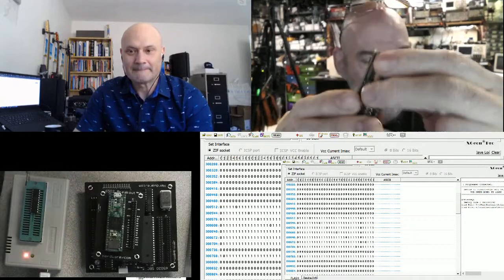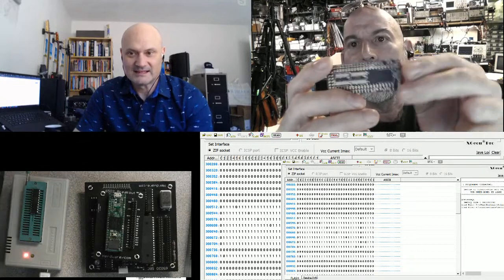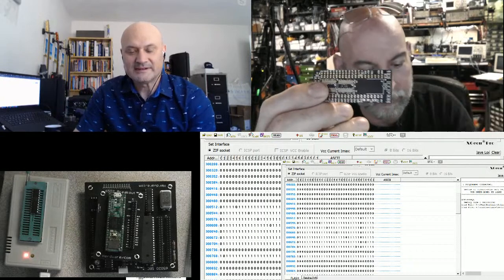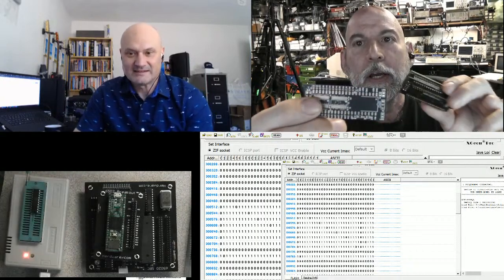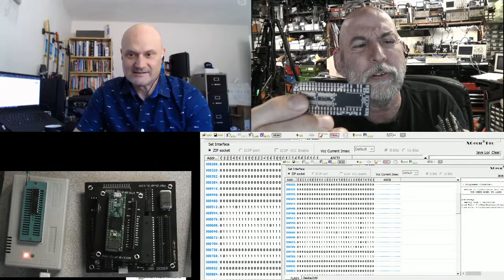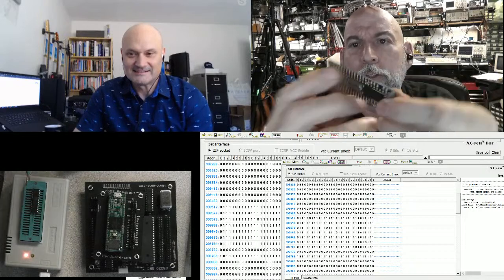So what I did was I did a board, and we've talked about this before, that underneath the part, I've got my line buffers and whatnot. Things that were strictly inputs, I forget, there's 5-volt tolerance, but then there's when you actually have to do level shifters.